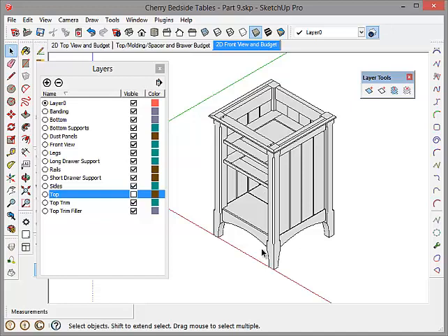That's more than enough for expansion, but it'll also allow the drawer to move freely as we slide it in and out. The side dimension, the opening width was 14 inches. I want to leave a 1/16 of an inch on each side to make sure things don't rub. So the overall dimension will be 13 7/8. And lastly, the box depth, I already left 3/8 of an inch, bringing it to 15. So we'll stay with 15 for the box depth.